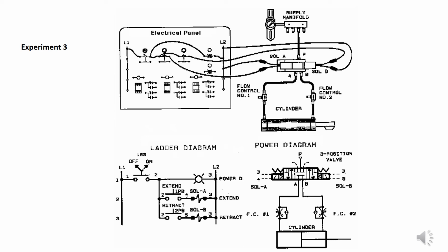So turning the selector switch to on provides power for the circuit. Whenever the selector switch is in the on position, the light will be lit. Power will be supplied to 1 and 2 PB, which, as in the previous circuit, causes the cylinder to extend and retract.